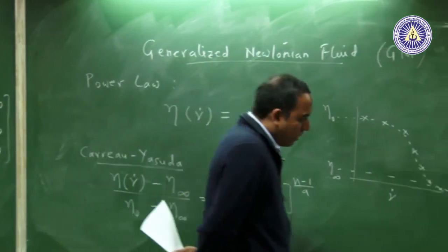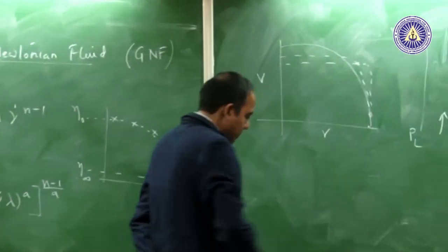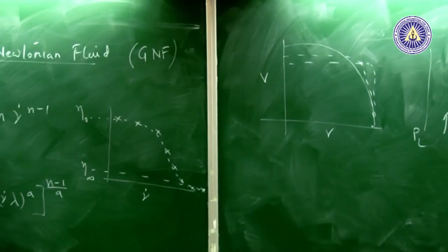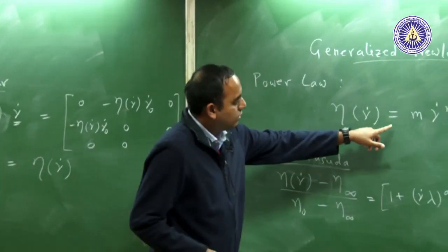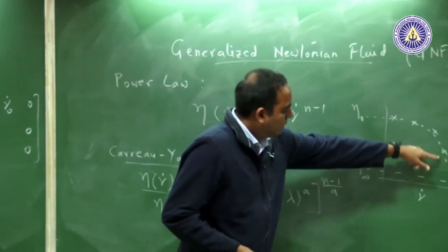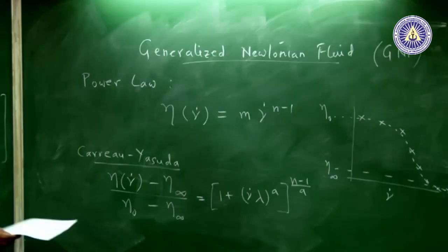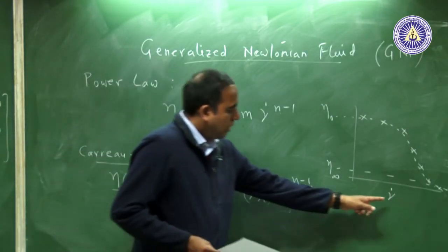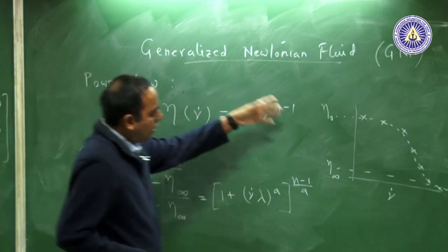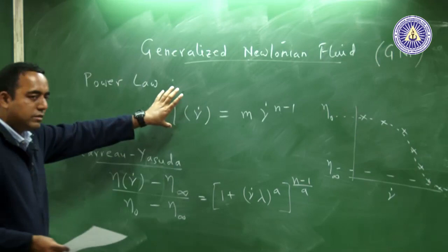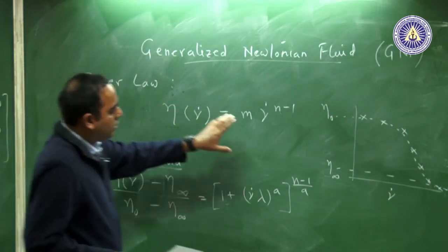Now, what I wanted to highlight is that the nature of the flow itself, the velocity profile itself, changes when you put in such adjustments that you get from the data. So, here you have done some adjustments to the data. You have seen the functional form of the viscosity with respect to gamma dot. You have put that functional form in, and as a result, with the power law, because of its relative simplicity, you can still do analytical computations and get velocity profiles like this.